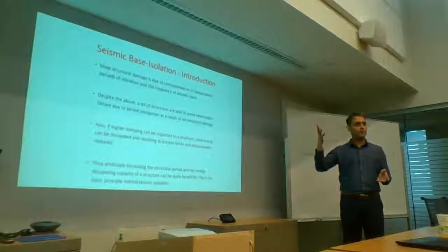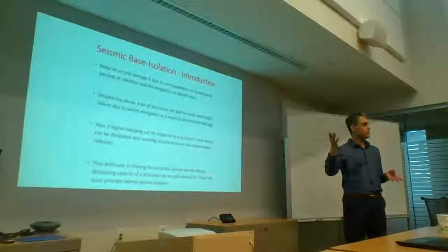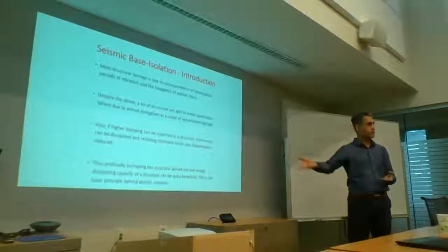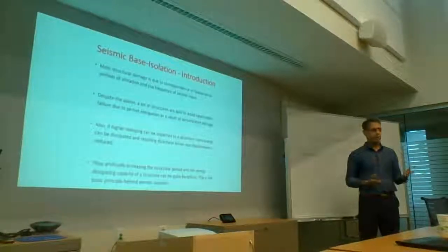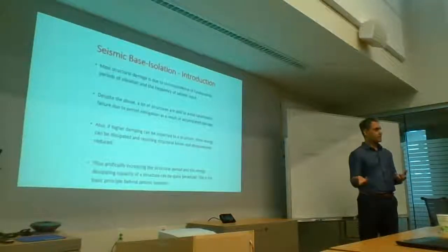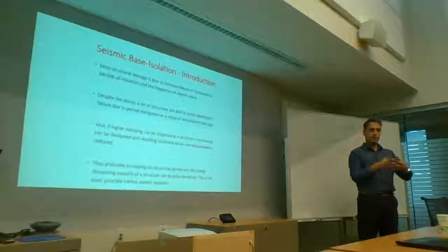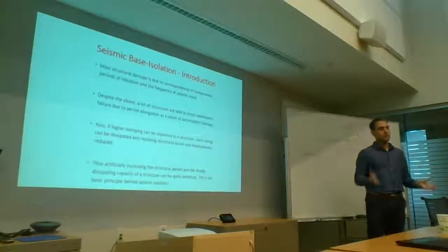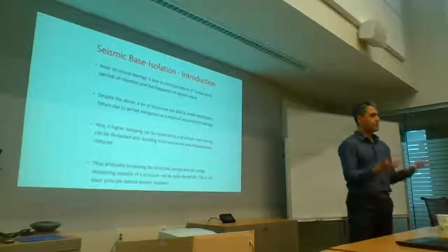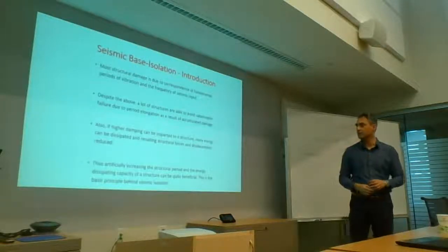Now think about a 50-story building in Vancouver and Cascadia hits, and that's a 3-second plus building or 4-second plus building where now Cascadia is bringing in a lot of energy. That's what's going to create problems. Sometimes what happens is the structures, if they have this ductility capacity as they damage, their stiffness goes down, their fundamental period changes, and they're able to survive the rest of the earthquake. If it's rich in that band, now it's moved out of it, it's not going to keep behaving in a very inelastic manner. The period is going to change, and hopefully the correspondence is broken between the two.